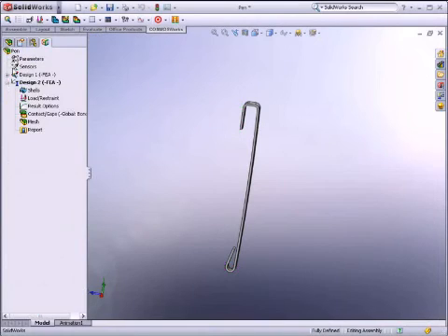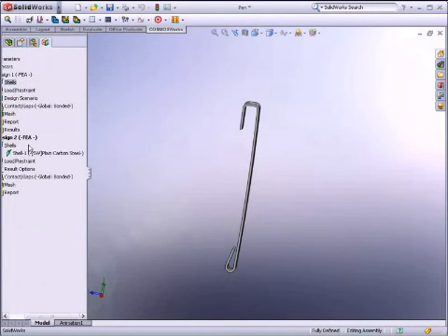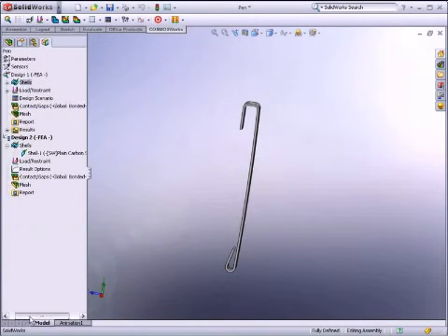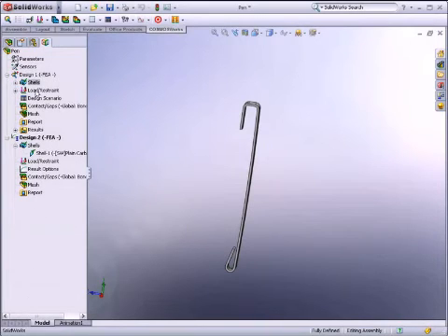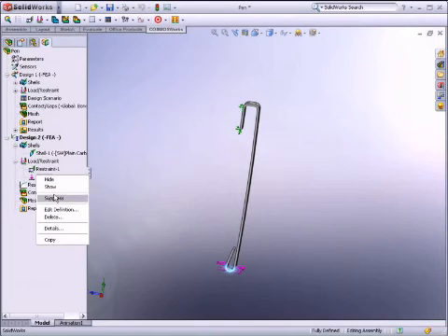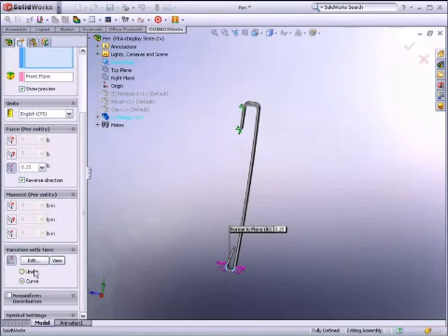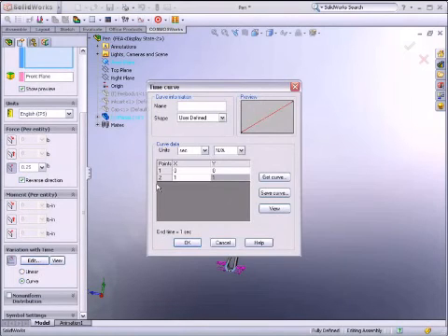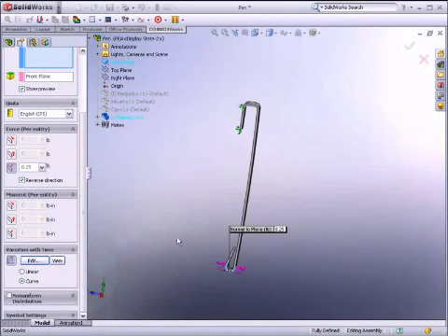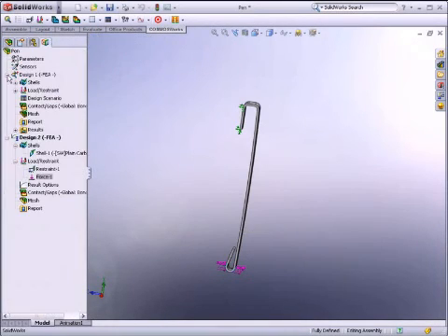We will run the same test over again, this time using a nonlinear analysis. With SolidWorks Simulation, you can simply copy the shells, loads, and restraints, saving time and ensuring consistency. We can easily modify the load condition so it varies over time using the curve option. In this example, we will create a simple curve that represents the load applied. This will allow you to see the deflection after the load is released from the model.